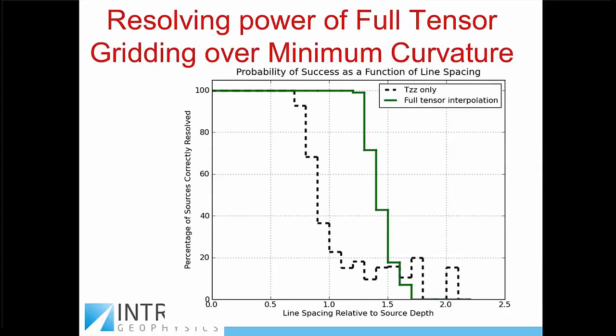Here's a graphic that Bell Geospace produced a couple of years ago, which was designed to demonstrate the ability of decreasing the cell size when you have the full tensor measurement. More or less, traditional gridding would give you a cell size of 1/4 of the spacing between the lines, and this would go to 1/6 or 1/7 as soon as you have the full tensor available.